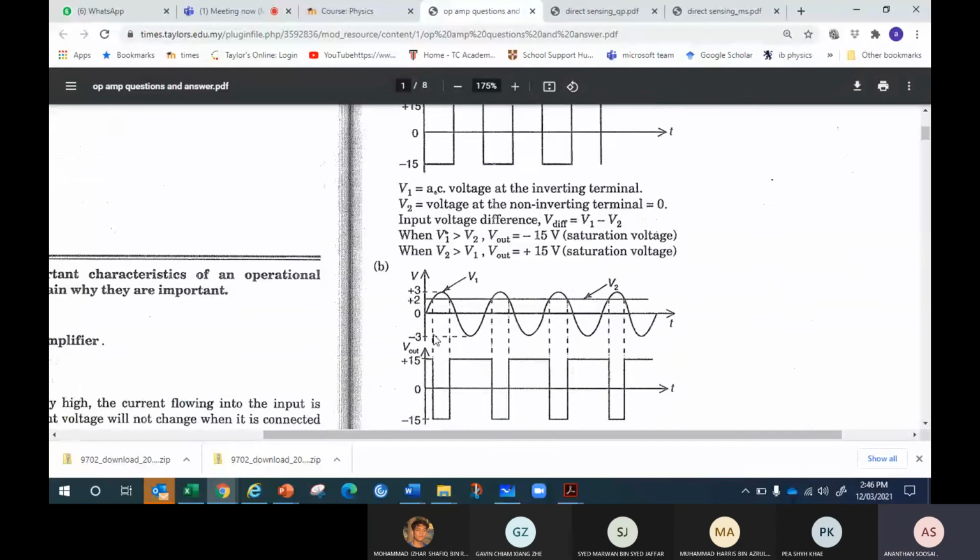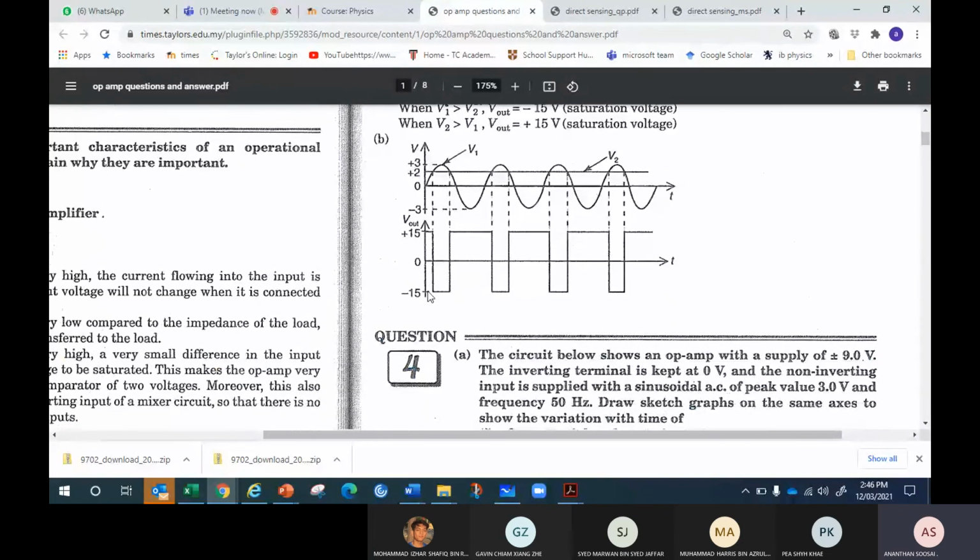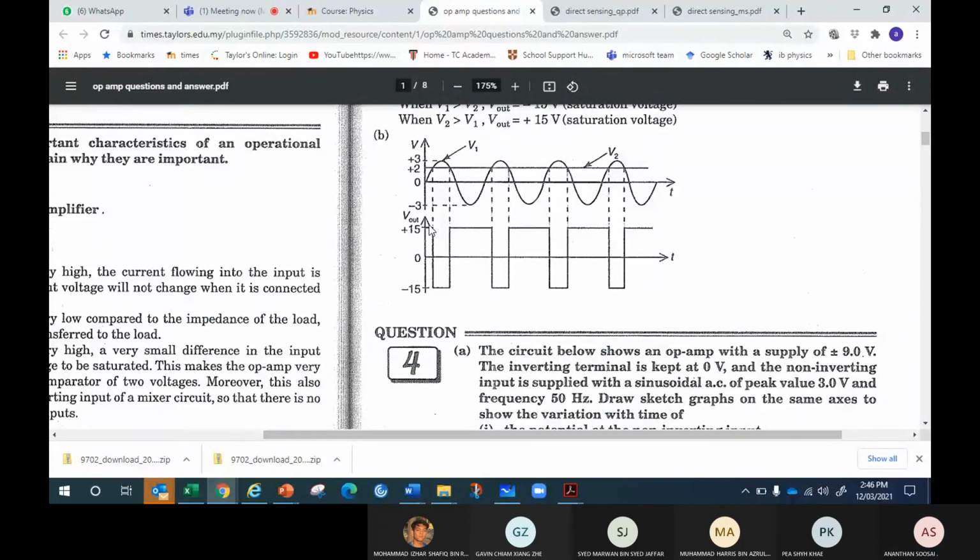Last time we just inverted the graph because the positive didn't have anything. But now the positive has 2 volt, so the positive is going to be the winner partially at the beginning. At the beginning positive 2 is greater, so the output will be positive. In the exam, they will ask you to trace this. Any questions? Hope you understand how to trace. The positive input is now actually a voltage instead of 0. Last time it was 0 volt, now it is given 2 volt.